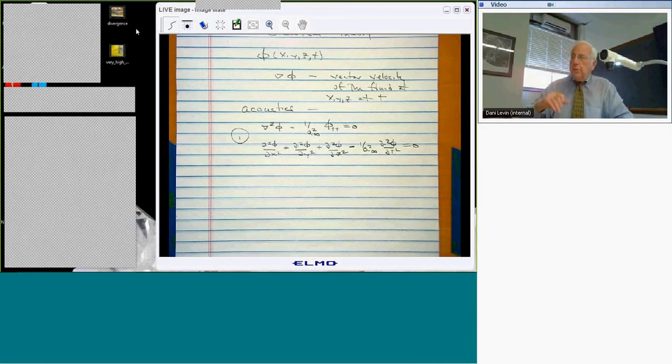And so then we have to distinguish between waves going out and waves going in, and based on ad hoc physical reasoning, we say, well, the waves must start at the airfoil. That's the only thing that's disturbing the fluid, and they must go out. There aren't any airfoils out at infinity unless someone's out there doing something, or come back in. We assume there's no one out there.